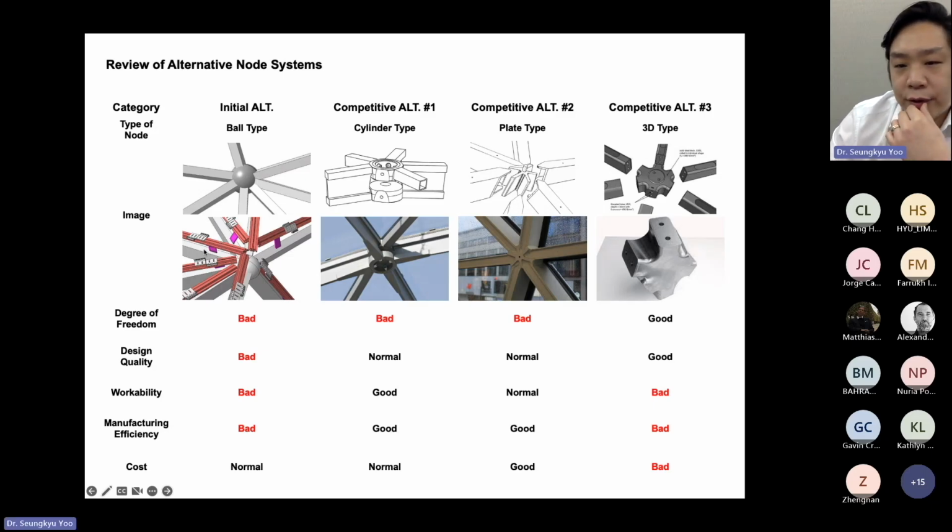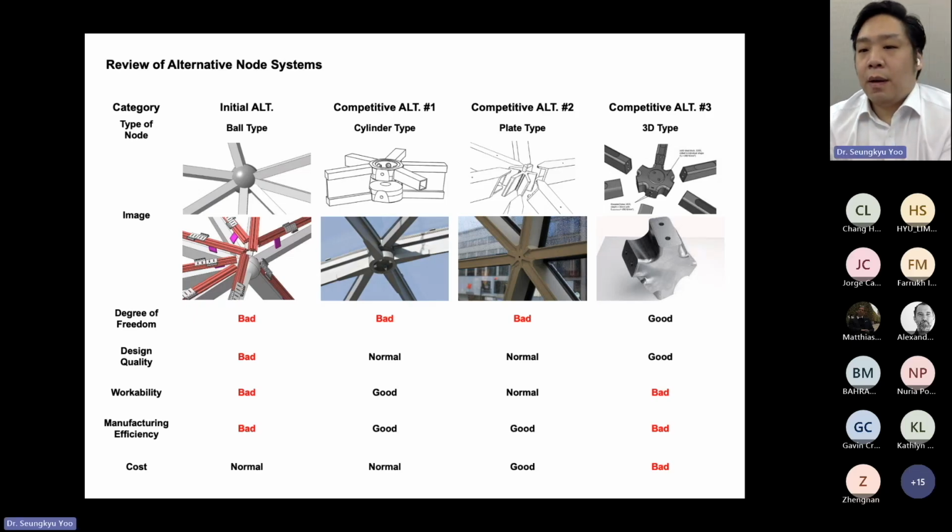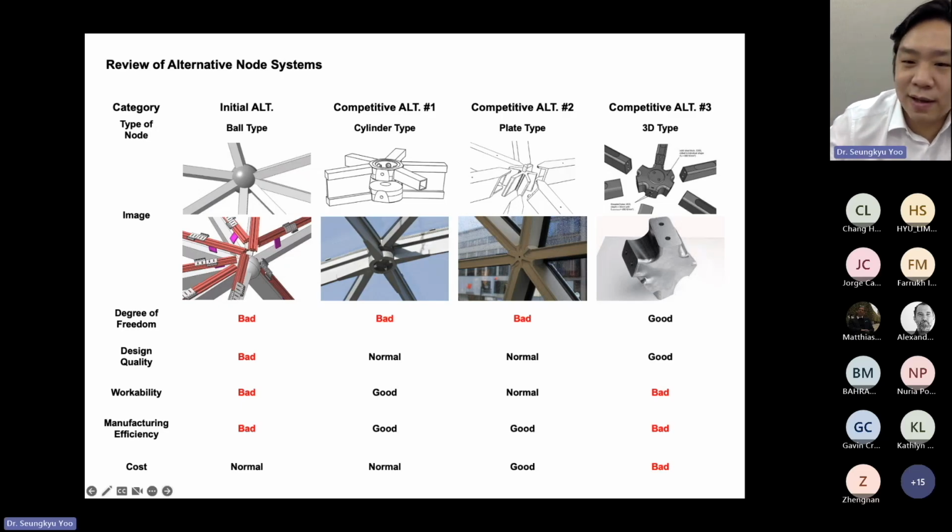Definitely, poor outer and inner finish and glass panel procurement problems would occur. Think about it. Each glass panel size must be measured individually and ordered after completing one triangle structure. As I mentioned, there are a total of 652 glass panels. Yeah, we can do that.